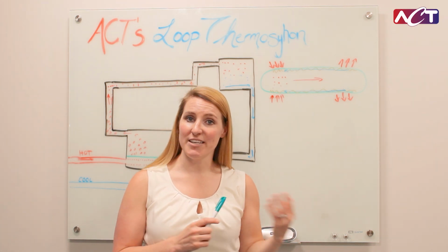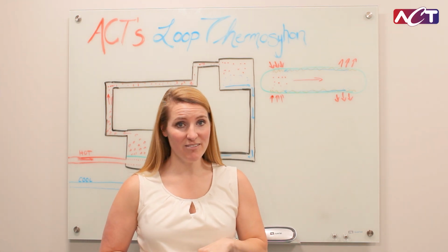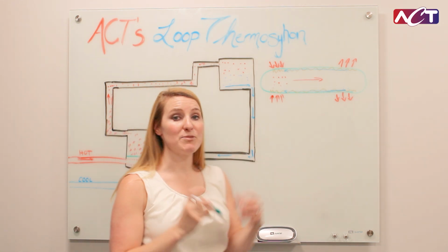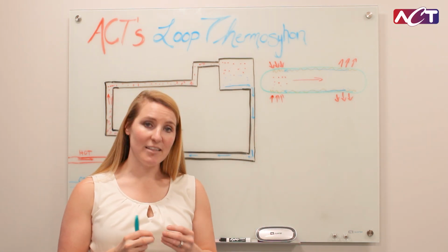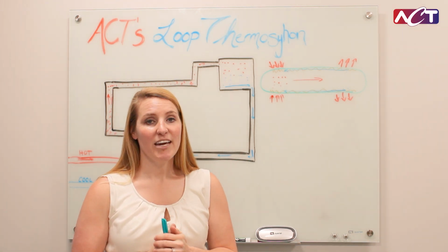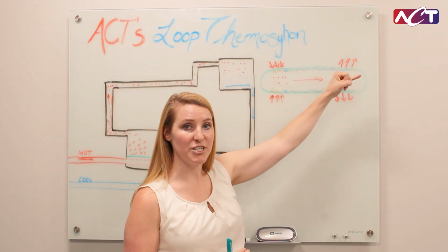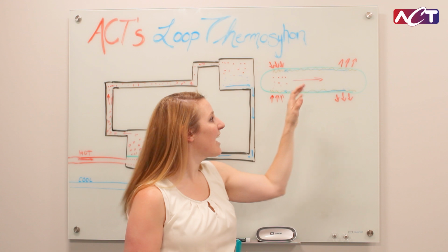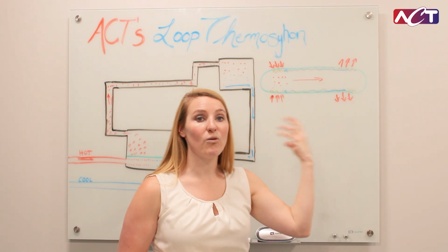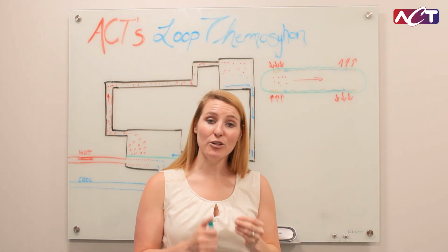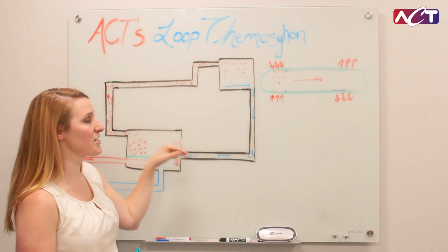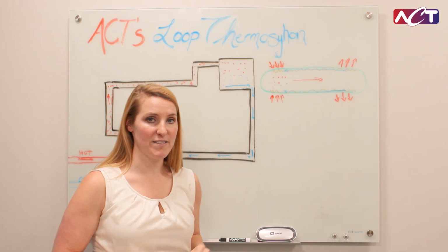So what's the difference between a standard thermosyphon and a loop thermosyphon? Well, here in this picture, you can see that our liquid and our vapor move in opposite directions. With heat pipes and thermosyphons, this means you hit the entrainment limit or the flooding limit. That's where, if you have high vapor pressure and high vapor velocity, you're going to pull some of that liquid out of the pipe or out of the wick, and so it won't return back to the hot spot. With a loop, you never have counteracting flows. You always flow in the same direction, which means we're able to handle higher amounts of power.